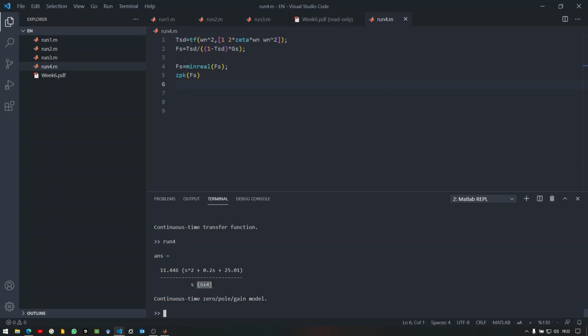Then we've modified our strategy in order to match the zeta value here, because we were restricted on the real axis. We have added the pole at -4 so that they would meet each other. These two poles in the loop transfer function would meet each other at -2, and they would then approach their asymptotes 90 degrees at that point. And since we were looking for the zeta times omega n multiplication to be equal to 2, the middle point of these would be giving us 2, which also would lead to the settling time of 2 seconds.